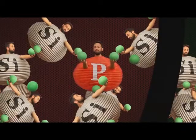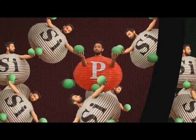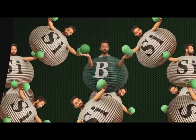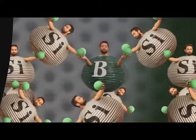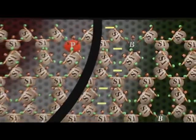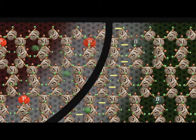When a transistor is made, the N and P types don't keep to themselves. Electrons actually diffuse from the N type, where there are more of them, into the P type to fill the holes. This creates something called the depletion layer. What's been depleted? Charges that can move. There are no more free electrons in the N type. Why? Because they've filled the holes in the P type. Now this makes the P-type negative thanks to the added electrons. And this is important because the P-type will now repel any electrons that try to come across from the N-type. So the depletion layer actually acts as a barrier, preventing the flow of electric current through the transistor.